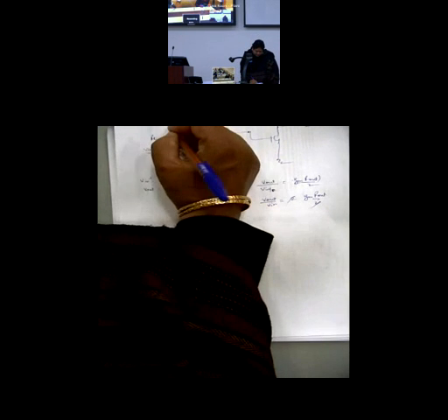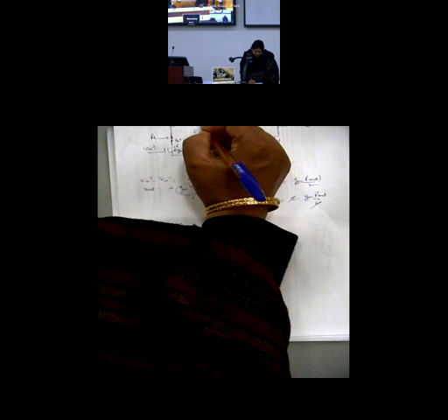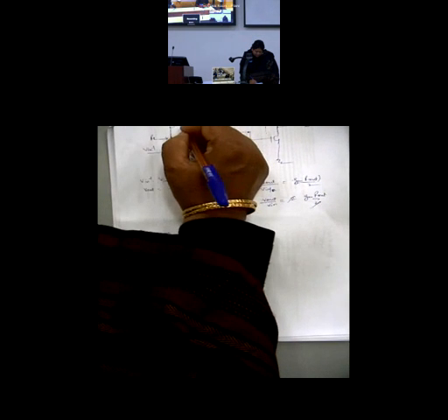So I need to mirror. The moment you have a mirror, there has to be a current mirror. So I put a current mirror. Now this current mirror has to be PMOS because it is connected to the source. I put a current mirror here.